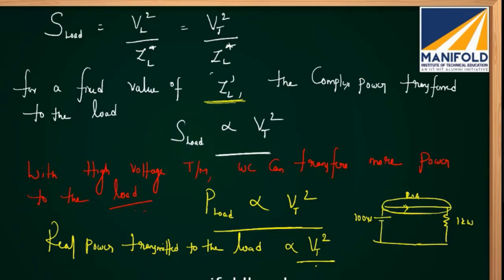So here, in order to send 10 ampere current, the cross section of the conductor will be lesser. In order to carry 20 ampere, the size or cross section of the conductor will be more. Understand? So when I go for higher and higher transmission voltage, to transfer the same power my transmission current reduces, with which the volume of material required to commission a transmission line reduces. Yes or no? Yes. Okay, this is an advantage.